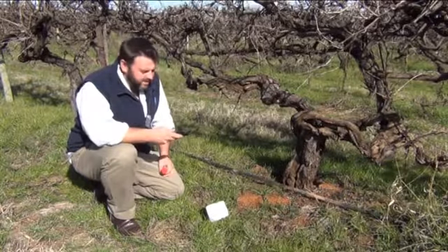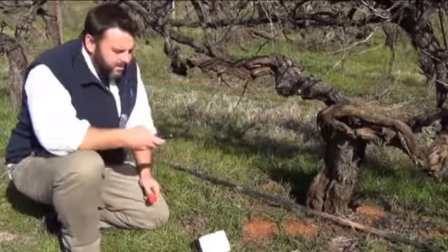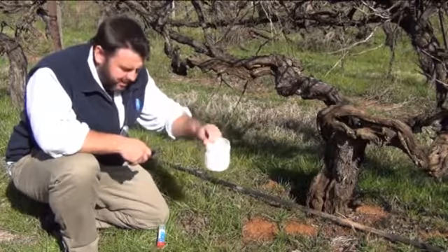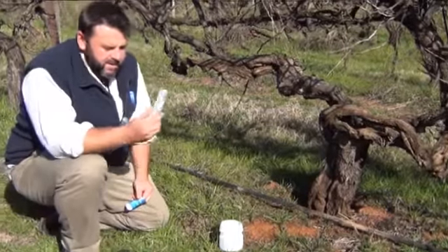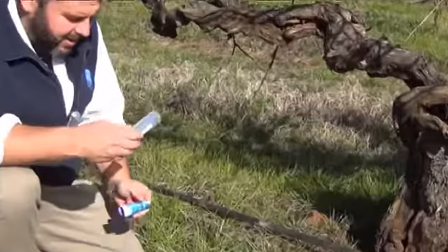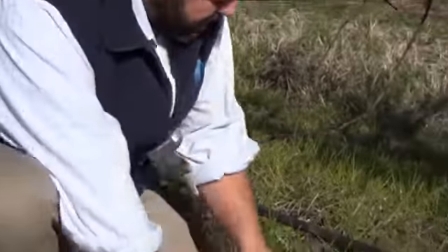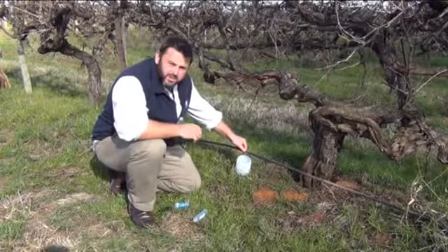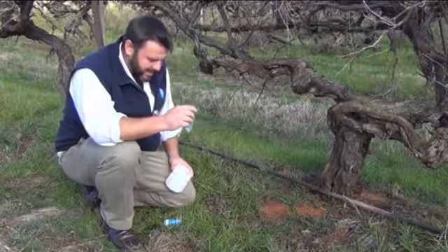Okay, after we've taken those basic measurements, what we now need to do is to measure the application rate of our systems. To do that, what we want is a simple container to be able to collect the water which drips out from the irrigation system, and secondly, some way to be able to measure that volume of water. These are just small measuring cylinders which are available from CSIRO that includes information on the online DU tool as well and how to undertake sampling. Once we've got this particular vial, it's a simple matter of actually measuring the drip application rate for 30 seconds to a minute, and then recording that information and the volume which goes out of the irrigation system.